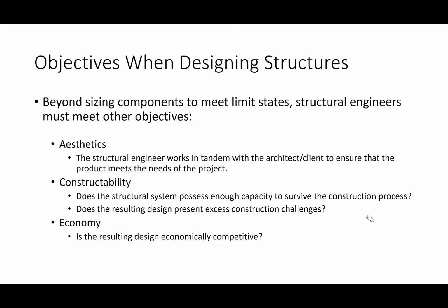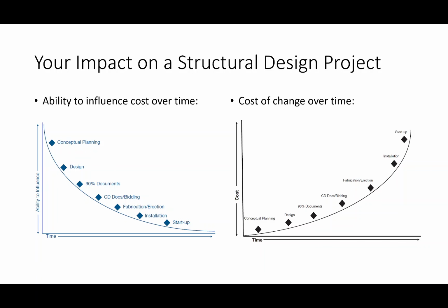What happens when the bolts get too far apart? Well, if you have two plates and the bolts are really, really far apart, when you tighten those bolts, you're going to get a little gap between the plates. And what can get in between that gap that steel is really going to hate? Well, what causes rust? Water, right? So if you don't have enough bolts to ensure a tight fit between the plates, you could get water in between your plates, and that could cause corrosion, right? So while we may not handle this directly, there are some limits that we do need to consider in that regard. Now I do want to mention this.